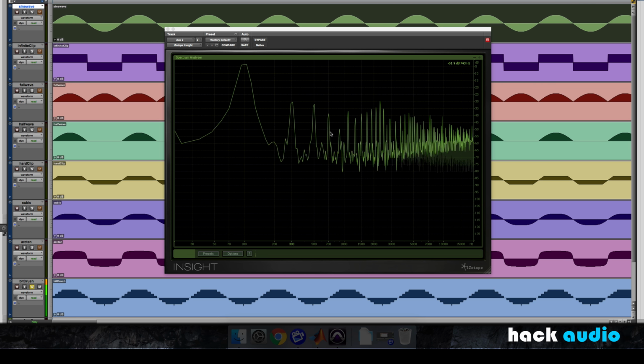One thing that's different is there's not an obvious pattern or roll-off to what's happening with these harmonics. In fact, up the spectrum towards Nyquist, we're still going to have these harmonics that occur at a relatively similar amplitude. This is actually a reason why it's important to do things like dithering whenever you're changing the bit depth on a signal.